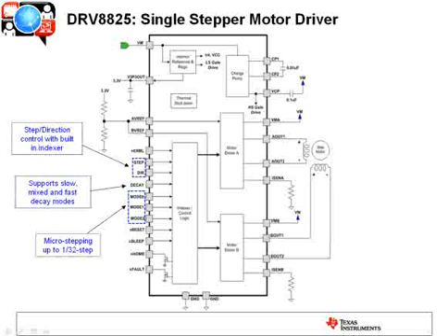In terms of the interface, this is the index interface. You can see here you've got the step and direction pins. Every time the step is pulsed, the stepper is going to advance or retract one position depending upon the polarity on the direction pin. You can set the decay mode. This device, when the winding current's increasing, is in slow decay mode, but when the current is decreasing, you've got a choice here. You can actually pick and tell it to decay in slow mode, fast mode, or a mixed mode, which mixed mode is 75% in, I believe, slow decay, and then 25% in fast decay.